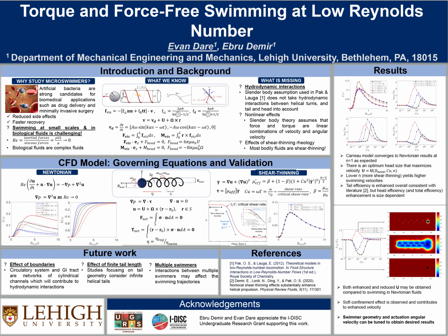Shear thinning. Next, to extend our study to the shear-thinning medium, we need to solve the Navier-Stokes equations, taking shear-dependent viscosity into account, as the linear Stokes equation no longer applies. We chose the Carreau fluid model as the literature shows that it captures the shear-dependent behavior of bodily fluids very well. The Carreau model obeys the power law for intermediate shear rates, while it displays a near-constant, Newtonian-like viscosity at zero and infinite shear rate limits.